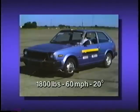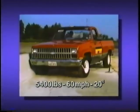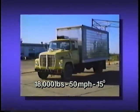The 1989 AASHTO guide specifications require tests with 3 types of vehicles: an 1,800-pound passenger car striking the barrier at 60 miles per hour at a 20-degree angle, a 5,400-pound pickup truck striking the rail at 60 miles per hour and 20 degrees, and an 18,000-pound single-unit truck striking the bridge rail at 50 miles per hour and 15 degrees.